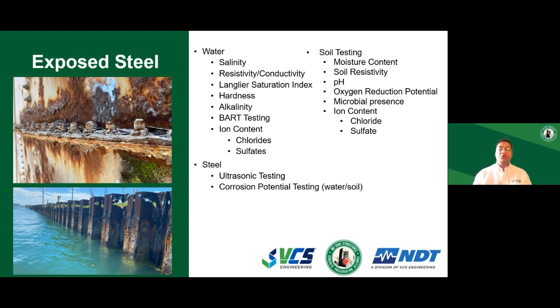When it comes to sheet pile walls, or let's say edge piles or steel piles exposed to soils, you need to have resistivity measurements of the soil. You need to have what the pH of the soil is, if the soil is acidic or not, if the soil is contaminated with chlorides or sulfates. Because if a steel element is exposed to soil contaminated with chlorides, then obviously it's a major risk in terms